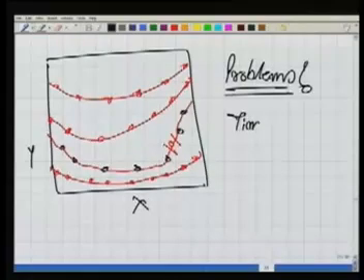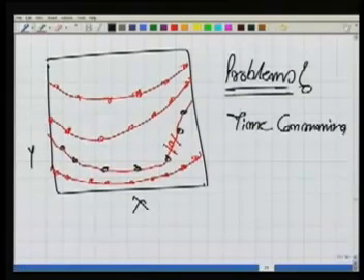So there is a lot of trial and error involved. You can't move your instrument. The instrument is fixed at the height of the instrument, making the horizontal plane. The only thing that you have to move is, of course, your staff, and the staff should also touch the ground. We know there is a point, but where is it, for which exactly 1 meter is being bisected? So this is a lot of trial and error. This method is really, very time consuming.